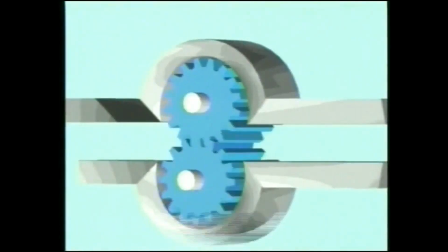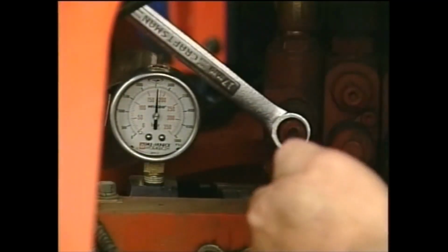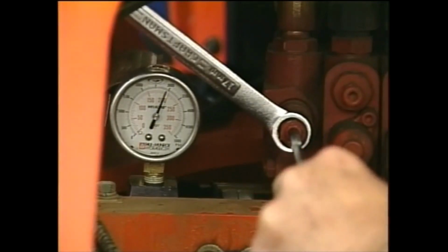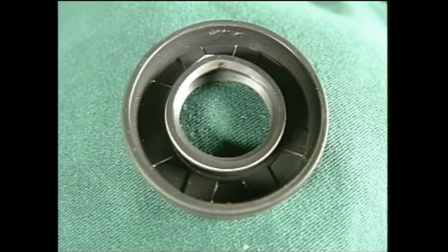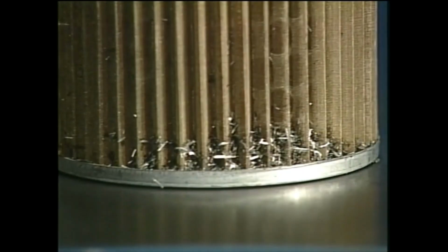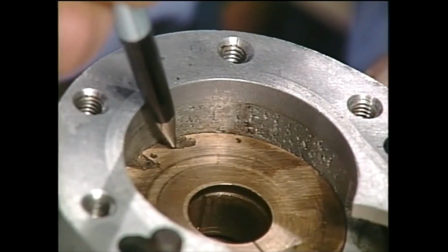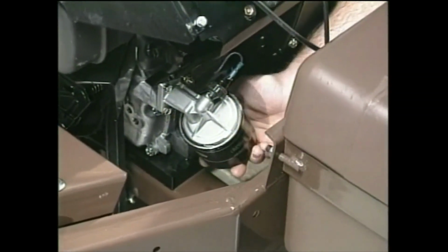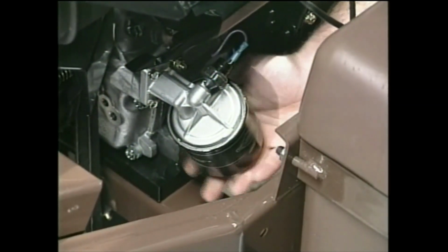Here are some important additional points about pumps. Pump shafts and pump bodies could break when relief valve pressure settings are increased above manufacturer specifications. Pump seals harden from excessively hot hydraulic oil. Pumps wear out from abrasives in the oil, such as rust particles, metal chips, and dirt. Pumps cavitate when the oil is too cold and viscous, or when the pump suction strainer becomes too restricted.